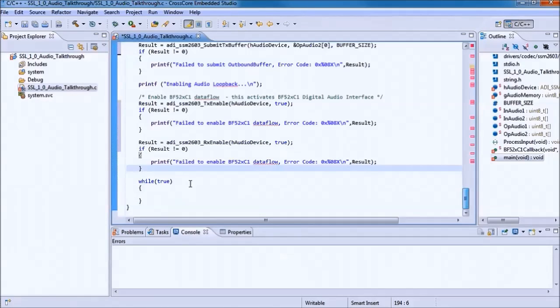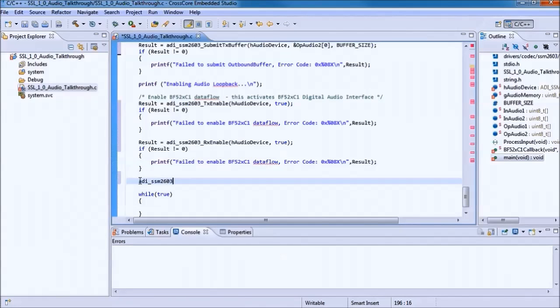As mentioned earlier, we also need to configure the volume, as that was originally taken care of through the ADI dev control call with the register field table write command. Instead, use the set volume API. This needs to be issued 4 times. A call for each of the left and right channels of the DAC, and a call for the left and right channels of the ADC.